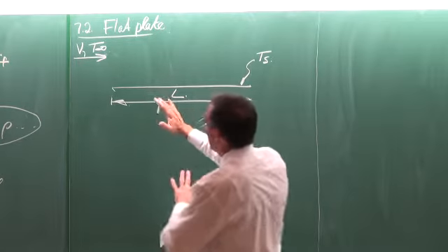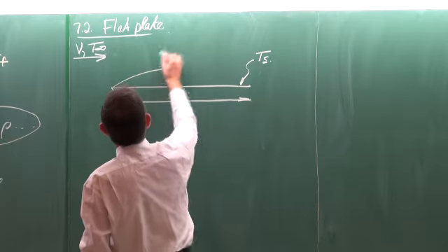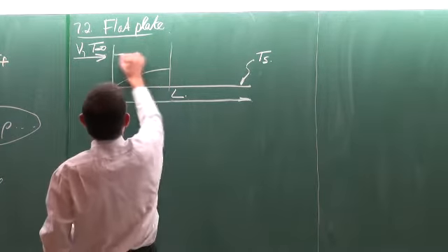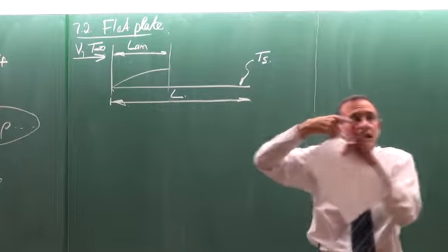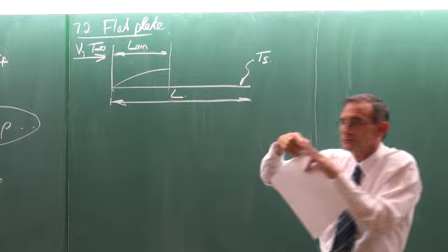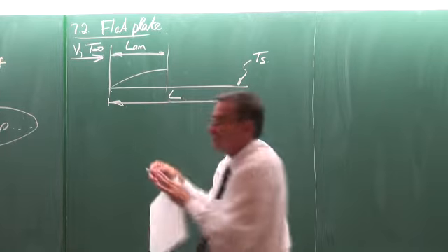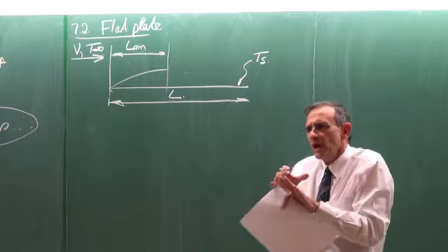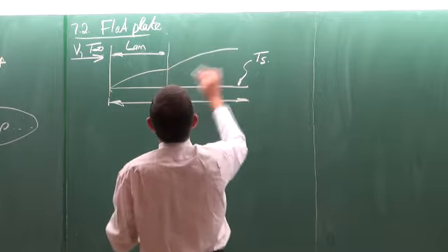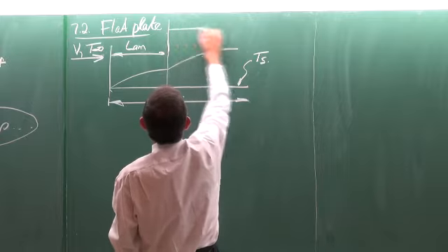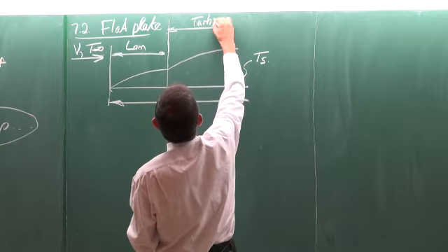What happens is we know that there is laminar flow in the first part. So that part is laminar. And we know there is also a part of transition. But to make things simpler, we are going to forget the transition part and work it into the turbulent part, and divide it into two separate areas: the laminar flow regime and the turbulent flow regime.